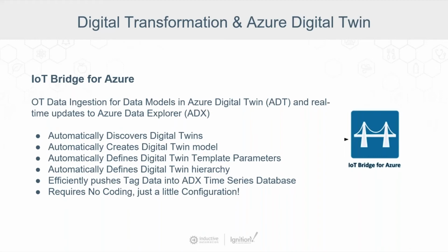And IoT Bridge is a service that can subscribe to an MQTT broker on one side, and it knows how to automatically create the digital twins in Azure Digital Twins. So you literally, from a no-coding aspect, can automatically discover all of the digital twins and the models that they're built out of.